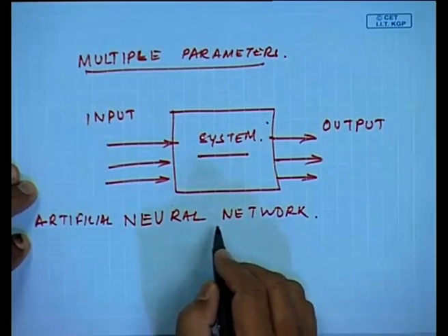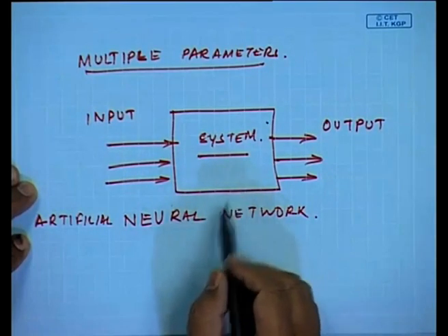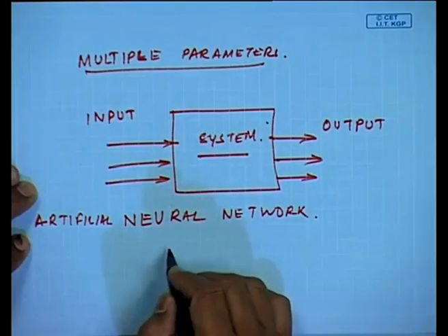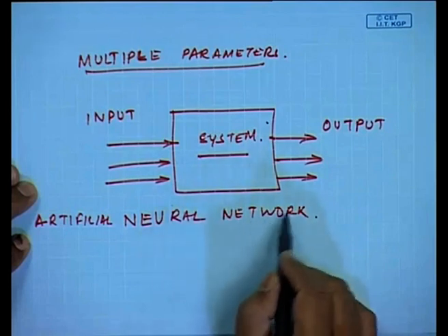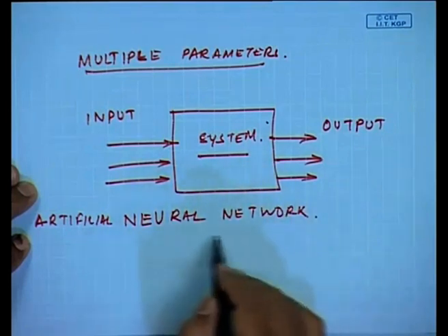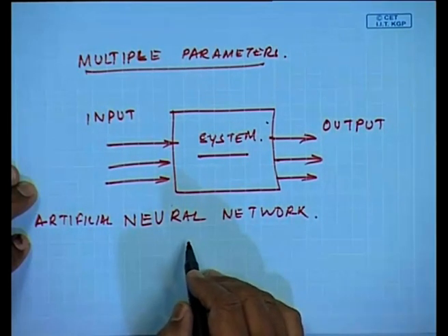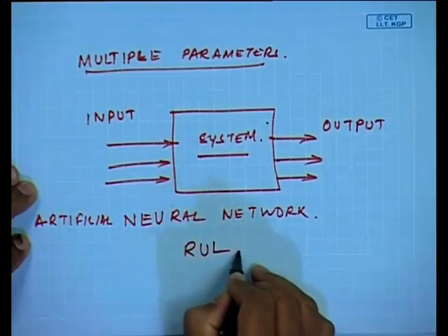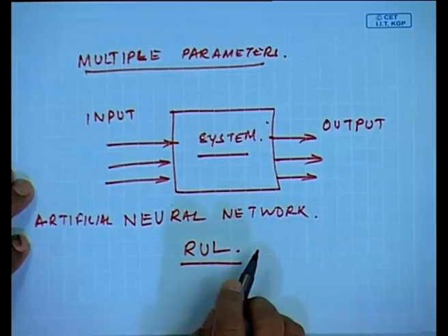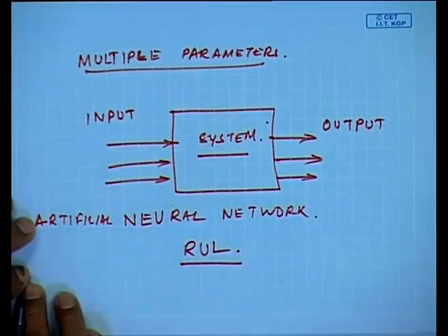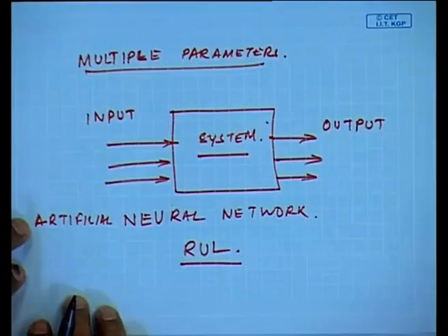to find a relationship between the input and output and come up with models as to what kind of output levels will be predicted as a function of time, and then we can estimate the remaining useful life by such a technique. There are many methods of RUL estimation. One is fuzzy logic classification, another is neural network classification, and the next one is wavelet neural network.